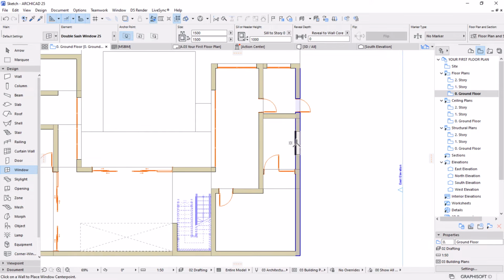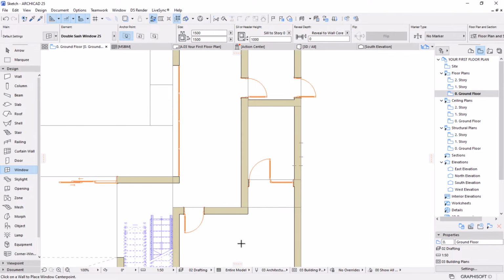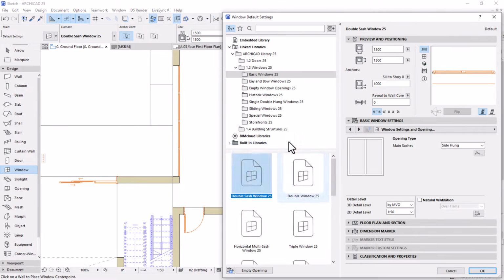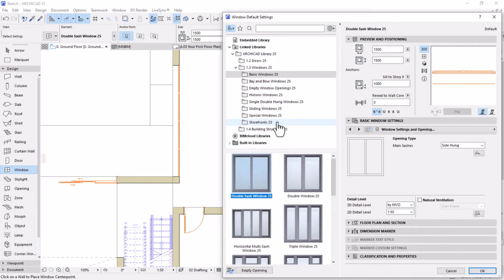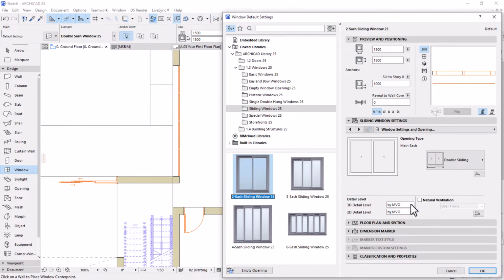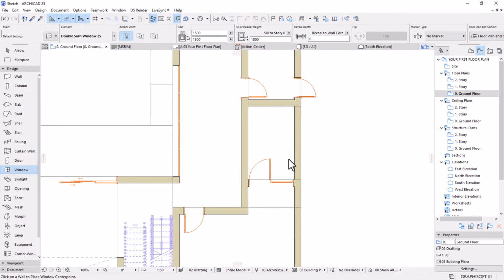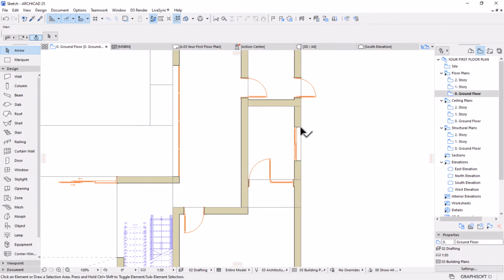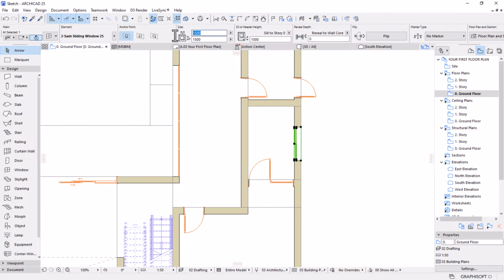So we have the bathroom, or the en-suite, for this bedroom. So this one I can change maybe the type of window to be, instead of sliding, okay, let's go for sliding as well. I can go for this, change this to 1:50, and then hit OK, place it centrally outside. I think I can increase the size of it to be maybe 2 meters under the size parameters.